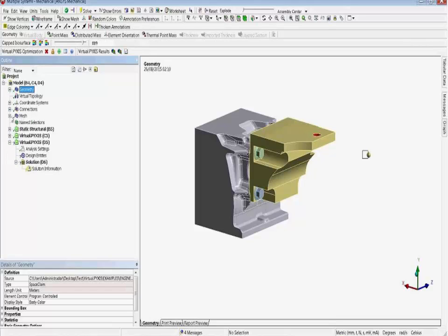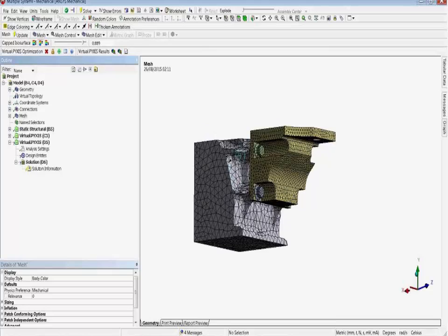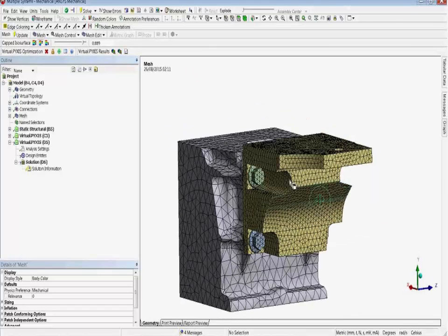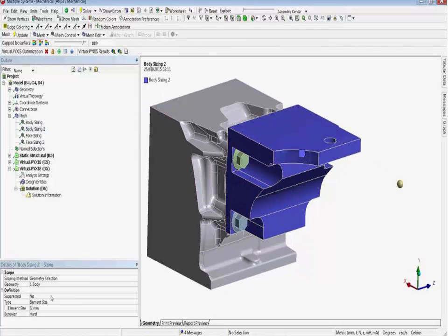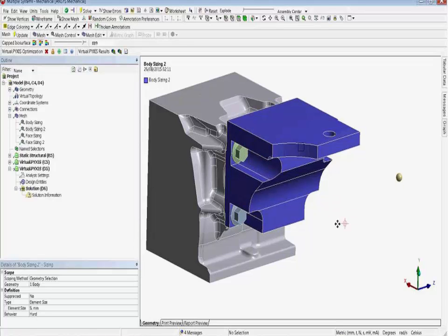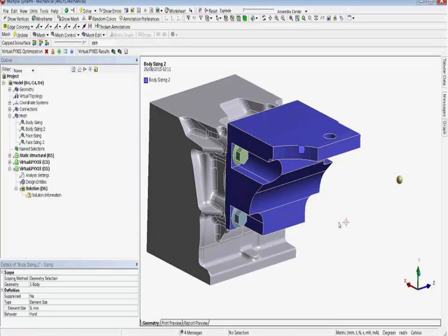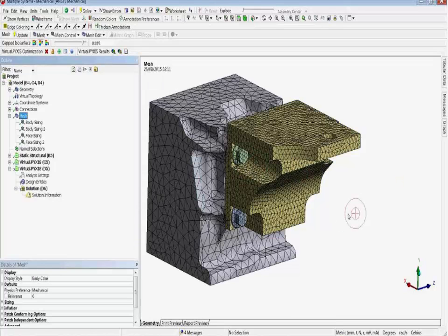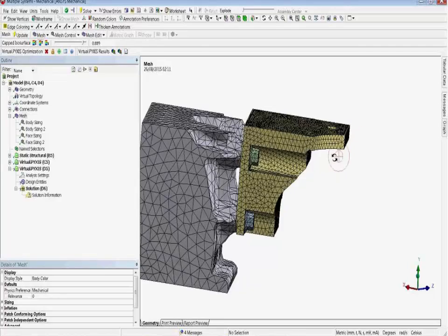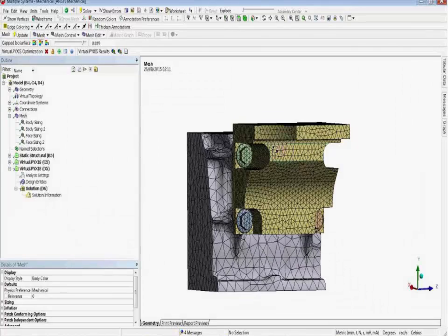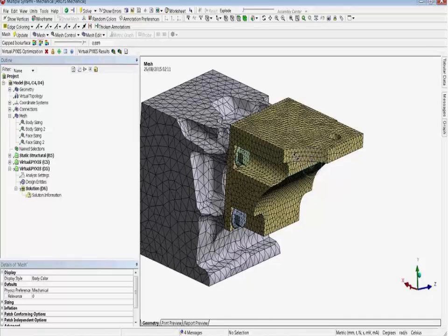So the mesh of my model here, I use 10 millimeters body size control for the support. Sorry, 5 millimeters, which is good for a topology optimization, because in this case you try to get a uniform element size for this component, which also gives you the possibility to get a better topology optimization result.